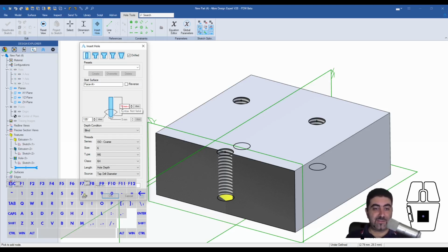And you see now that this has got an invalid syntax because it's not recognizing the diameter anymore, right? This D9 here, it's not recognized anymore because now the diameter is driven by the pre-selected tables of the hole tool. So this is not valid anymore.